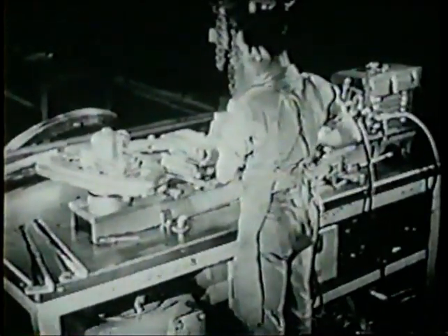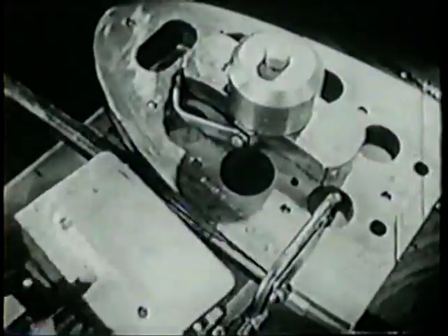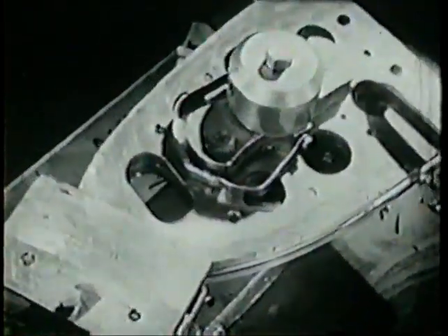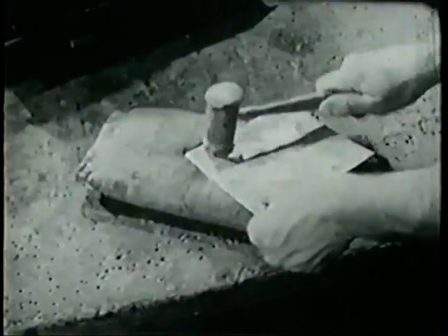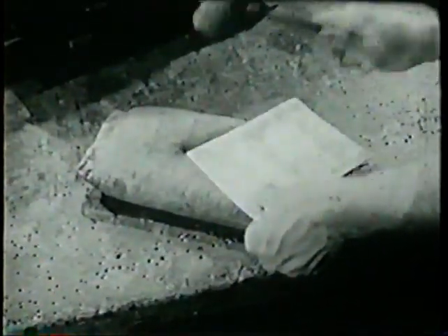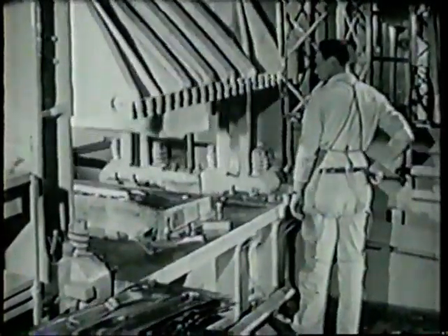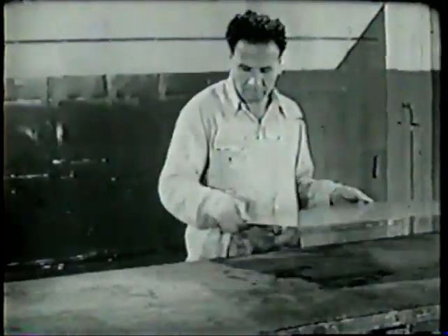Cold working of aluminum alloy is essentially the result of applying sufficient force to the metal to cause permanent deformation. This is true whether the force is applied by hand, by hammer, or through machines of large load capacity, such as the drop hammer. These operations result in strain hardening or strengthening of the metal. The basis of this lies in the aluminum alloy itself.